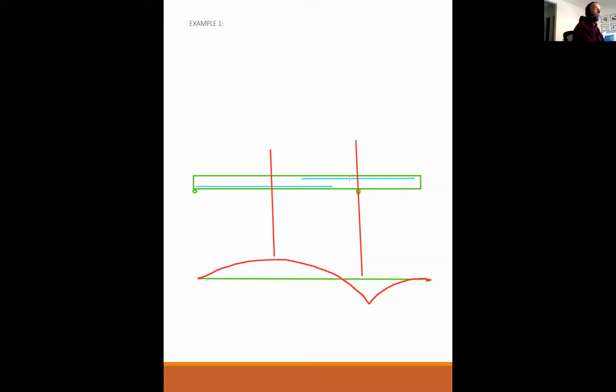You only had tension steel. So there's no discrepancy, because I only put the steel where I needed it to be. If I had done an analysis right here where the steels are overlapping, then I could have had a situation where this is still positive, so the steel in the top would have been acting like compression steel.